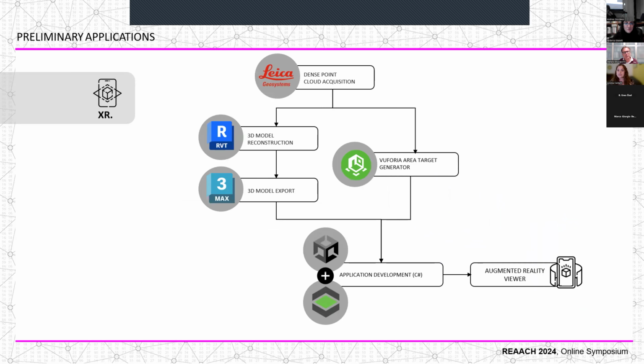To demonstrate the real-world application of the API and explore future possibilities in a more complex scenario, we conducted a survey of the Church of San Dominic in Salerno. We performed the site survey using a scanner to generate a point cloud in E57 format. Following the previously mentioned data collection methodology, we created a 3D model of the church and its installations using the point cloud as a basis for reconstructing the 3D model in Revit.